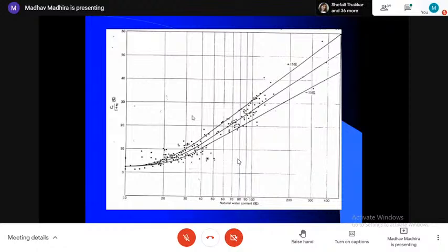The problem with many of our investigation agencies is they collect a sample and determine the water content after a week or 2 or even 3. At one site where I went, the water content according to us was more than 85, which is what we found out immediately. But the investigation agency gave us a value of 27. I asked them why. They said we had to send the sample from here to Chennai. It was tested, and they didn't seal it properly. And you can't keep it for 3 weeks. The water will escape and dry. So try to get the natural water content.